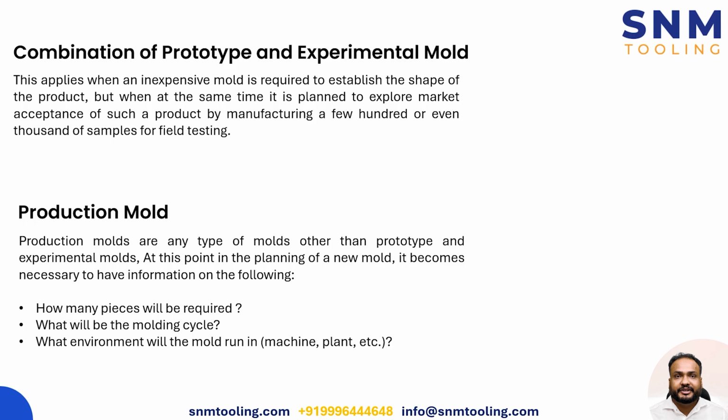Again, it's an inexpensive mold. Although it should be fully automatic, there is no need to make it 100% efficient. We can compromise on the efficiency by using suboptimal cooling channels, and we might not use a mold as expensive as a hot runner mold, right?